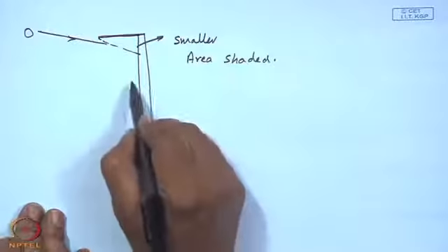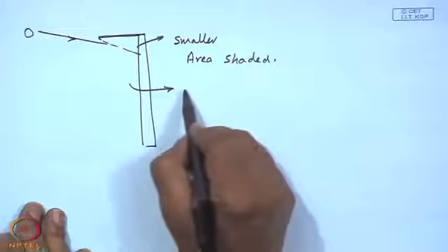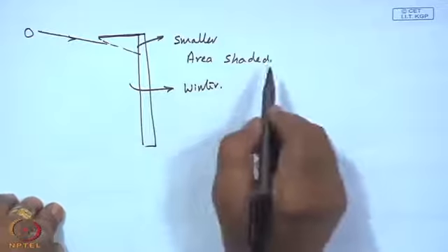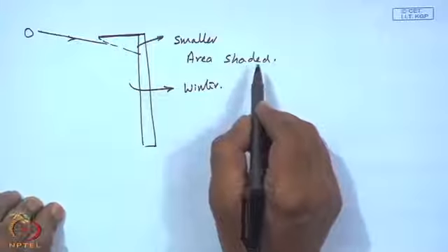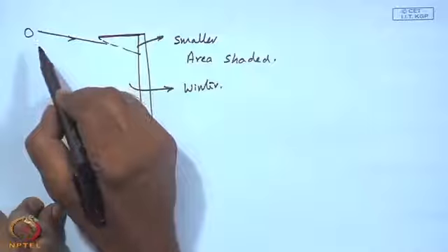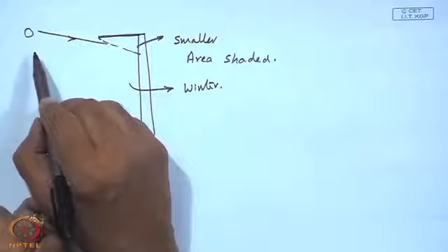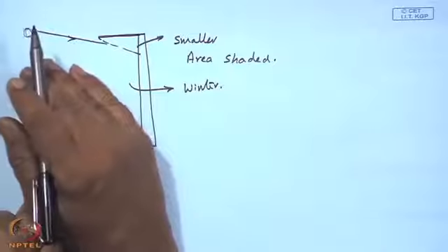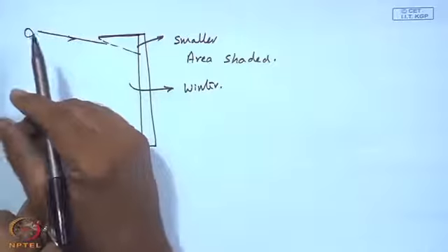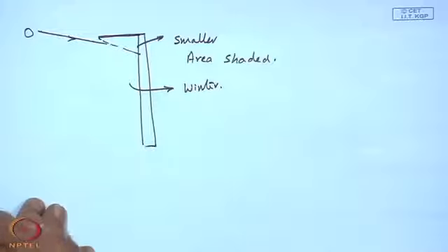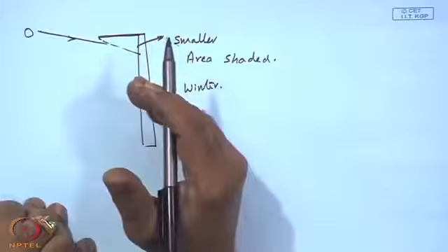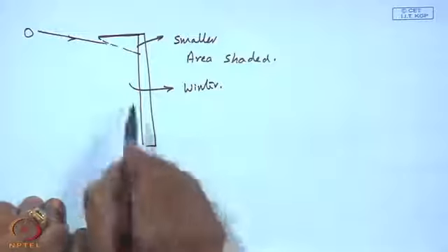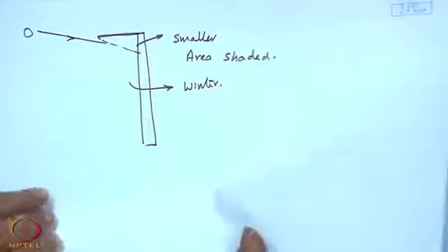So, it will let in the sun in winter, whereas it prevented so much sun from entering during summer. The positions of the sun, at least in the northern hemisphere, as shown here, it is pretty low in winter months or declination negative in general, and in summer months it will be high up, almost right above your head at noon time. So, consequently it casts a longer shadow shading the window.